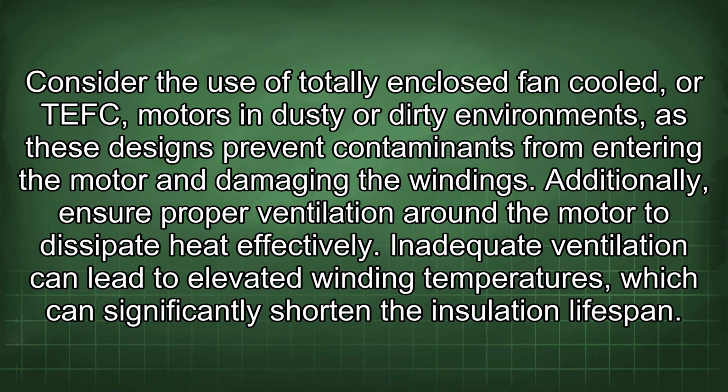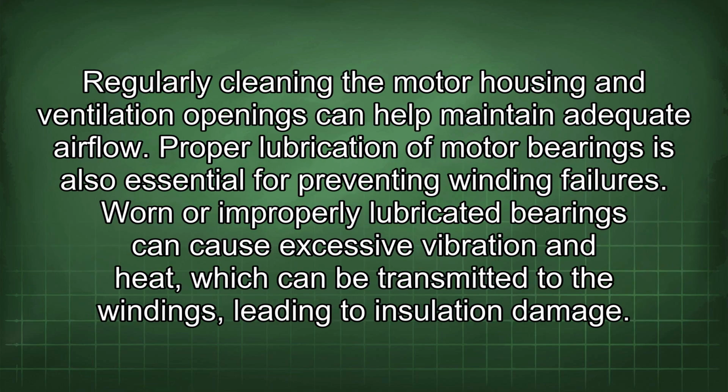Additionally, ensure proper ventilation around the motor to dissipate heat effectively. Inadequate ventilation can lead to elevated winding temperatures, which can significantly shorten the insulation lifespan. Regularly cleaning the motor housing and ventilation openings can help maintain adequate airflow. Proper lubrication of motor bearings is also essential for preventing winding failures.